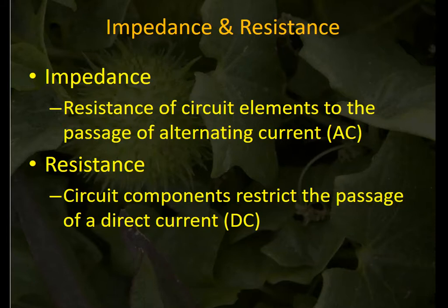Now we measure that in two different ways. The term impedance represents measuring that resistance using an alternating current. And typically it's a 10 hertz or 10 waves per second current that's introduced by the hardware, and it's introduced to the circuit. So we're actually running a 10 hertz electrical current, a very, very low ampere electrical current through this circuit to determine how much of a voltage drop we'll have between the beginning of it, where we know how much voltage we've generated on the initial end, and how much we measure when it comes around to the end of the closed circuit.